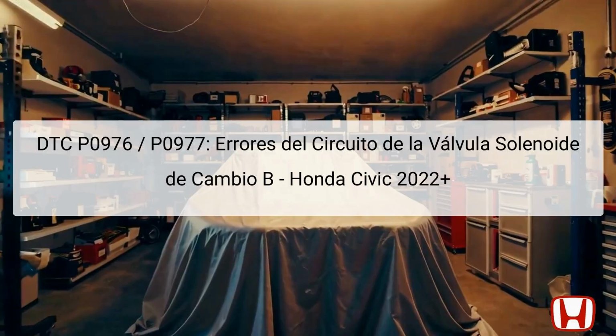This presentation addresses the diagnostic trouble codes DTC P0976 and P0977, which pertain to issues with the shift solenoid valve B in the Honda Civic 2022 and onwards. The DTC P0976 indicates a low circuit condition in the shift solenoid valve B, while P0977 signifies a high circuit condition. The Transmission Control Module, TCM, is responsible for managing these signals and determining operational efficacy for gear shifting.